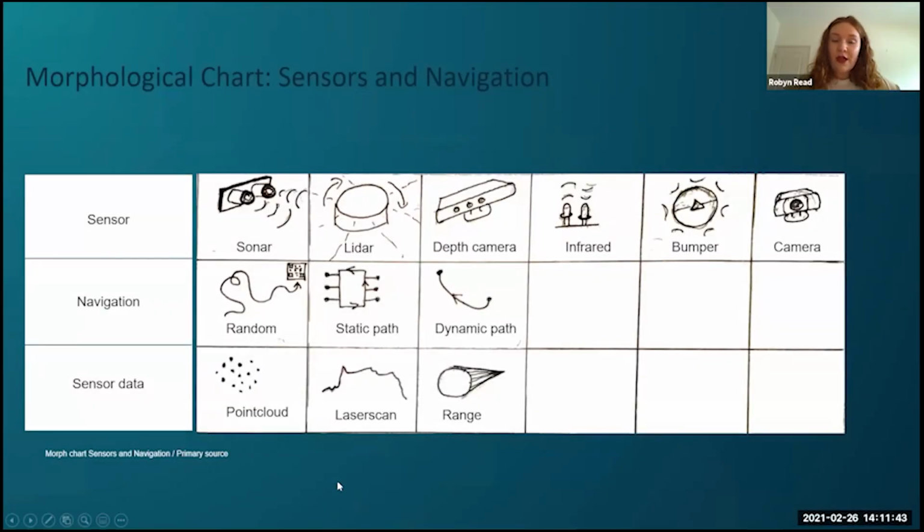We had three categories to go through in regards to sensors and navigation. For our obstacle detection, we chose to use the Kinect that you saw in the previous slide, as well as the pre-installed infrared sensors. They are used for determining the distance from the Robotino to the target. By using the Kinect alongside the infrared sensors, we are able to cover close and long-range obstacles, leaving the Robotino with virtually no blind spots. Additionally, we are using the bumper at the base of the Robotino, which is being used as an emergency stop if the Robotino were to come into contact with an obstacle.